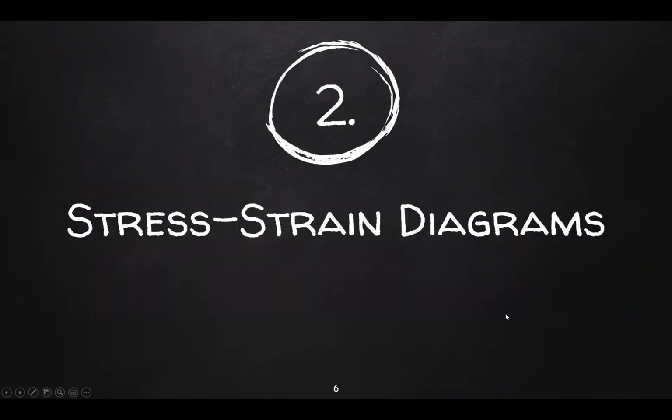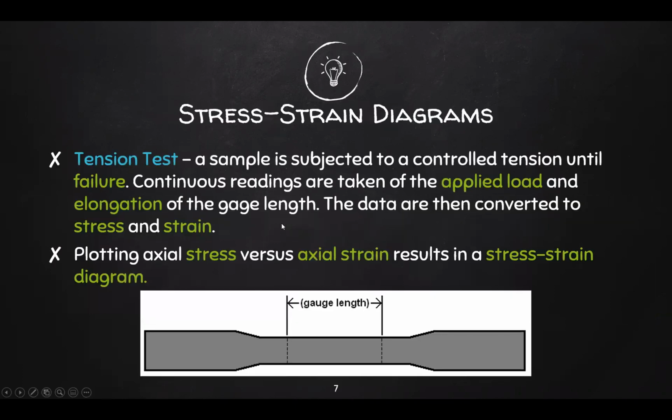Next, we have your stress-strain diagram. So to create a stress-strain diagram, we do a tension test. So under that, a sample is subjected to a controlled tension until failure. Continuous readings are taken of the applied load and elongation of the gauge length. The data are then converted to stress and strain. So for example, you have this rod, a sample. Gauge length is the original length taken from the sample. And then a continuous load is applied to that. Because of that load, it's going to stretch or elongate. And then you're going to compute or measure out that load and elongation. And then from those two, you can compute stress and strain.